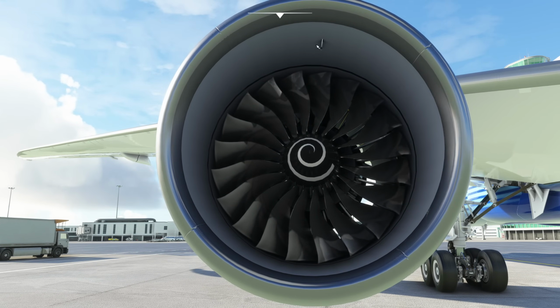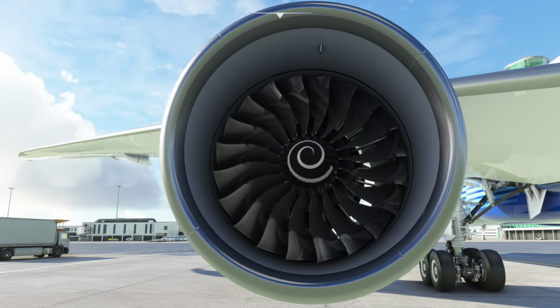This probe up here, which is nice to see modeled, is the TPR probe. So this being a Rolls-Royce engine, the primary engine instrument is not the N1 speed, which is this fan. It's called the N1 fan, and the speed at which it turns is often used as the thrust setting reference for these aircraft. Rolls-Royce used to use EPR, now it uses TPR using this little sensor here.